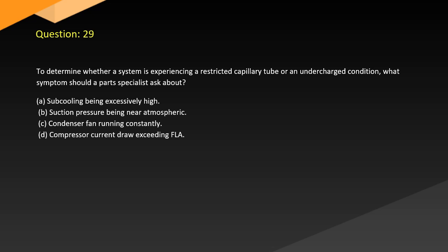Question 29. To determine whether a system is experiencing a restricted capillary tube or an undercharged condition, what symptoms should a parts specialist ask about? A. Subcooling being excessively high. B. Suction pressure being near atmospheric. C. Condenser fan running constantly. D. Compressor current draw exceeding FLA.